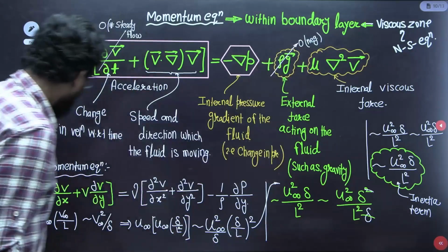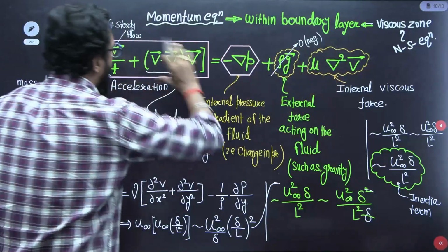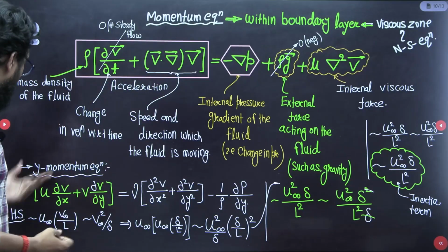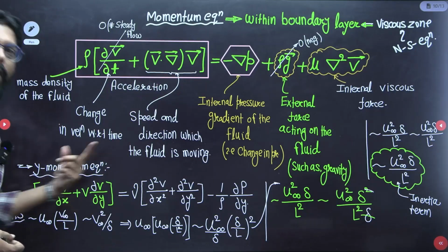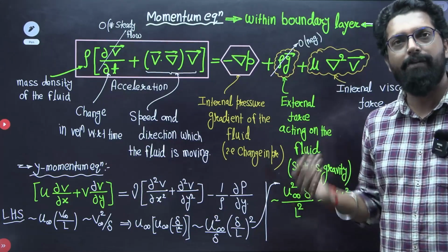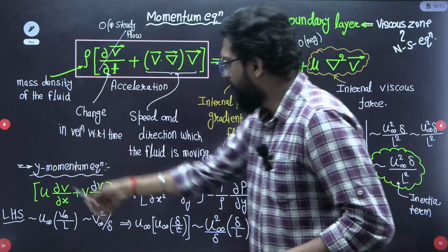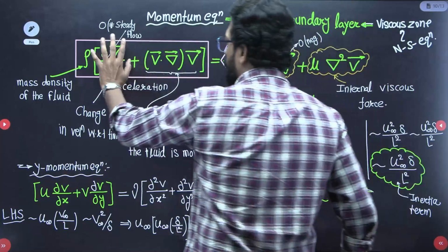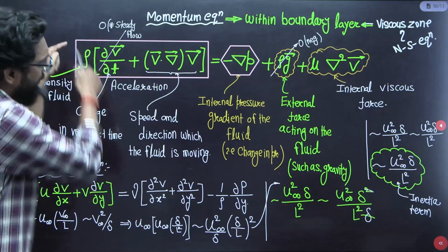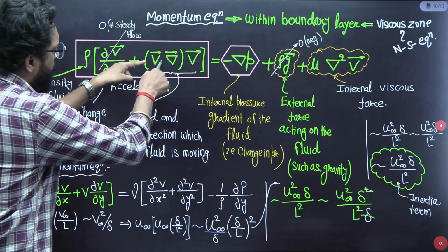Now, this equation is in a very compact differential and vector calculus form. Now we have to write the momentum equation explicitly, in the y direction first. Why x and y directions? Because we are only considering 2D flow. First we take the y direction momentum equation. If you split it, this term is 0. Second, you take the density and divide it to the right side. So this is 0 and v dot del into v vector.